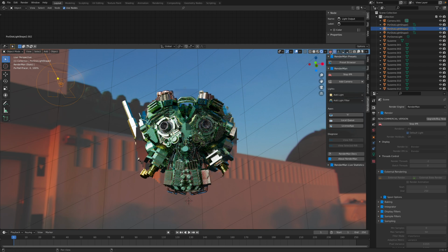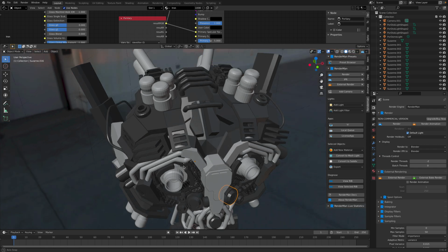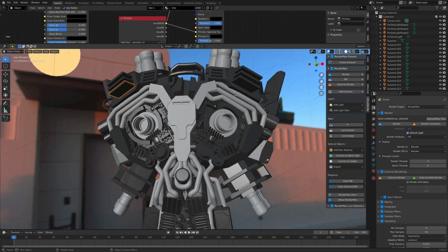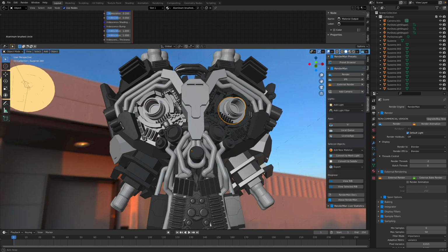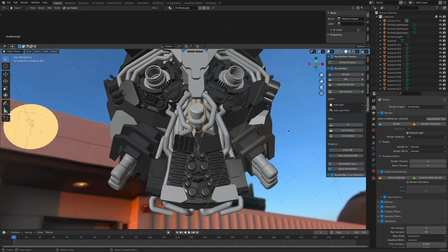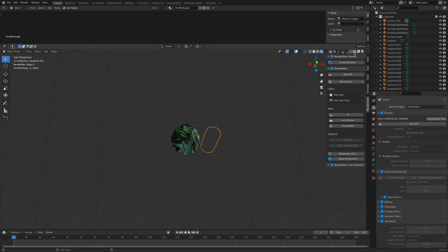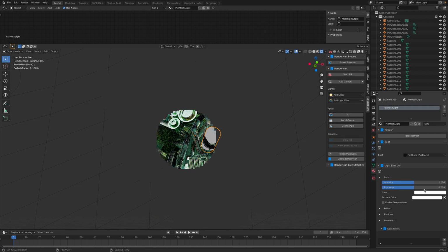What I often forget is to add something like light. I haven't tested it out, but we might be able to add things like light. Maybe the nose can be a light object. Convert to mesh light. Increase the intensity of the nose light. It should behave like light there. Kind of want it to glow as well.